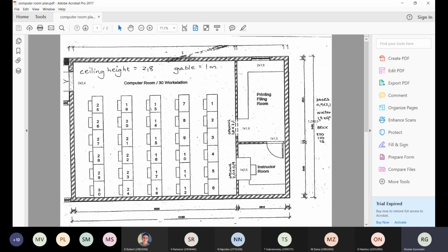Similarly, if you look at here, I'm also going to need two lintels, but the opening of the door is actually 0.9, 0.9. That's 1.8 meters. You agree? Then I need 300 on that side, 300 on this side, which gives me the 2.4. That's why I need 2 by 2.4 meter lintels there. Class, quickly, can I have your feedback? Are you all clear with that? Anyone? Does it make sense? Yes, no, class?